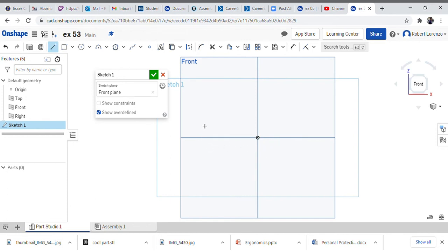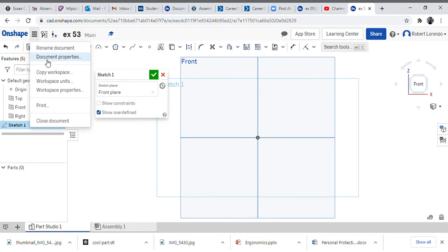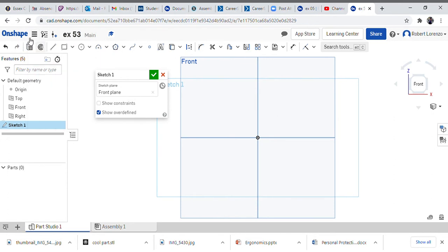Make sure it turns blue, right? And you'll also notice the origin turns orange. So I can just pick an arbitrary point and draw a line. Make sure again it's orange. Oh no, and I see right away I'm in inches, so let's escape out and convert our workspace units.